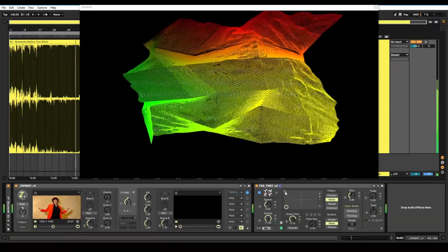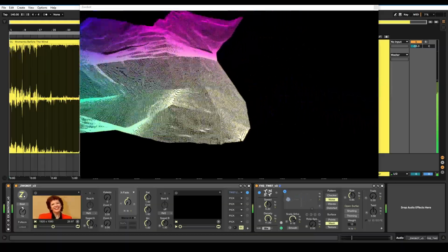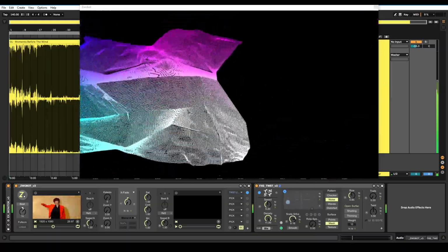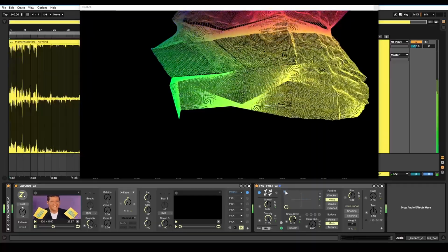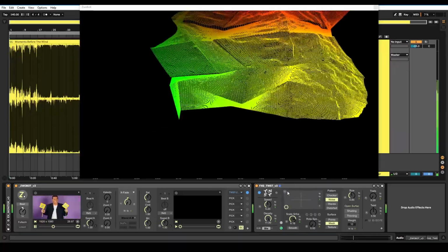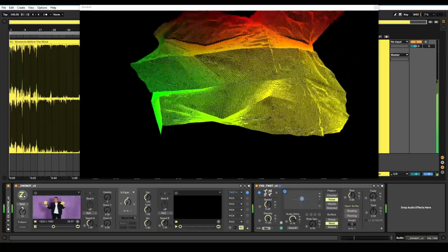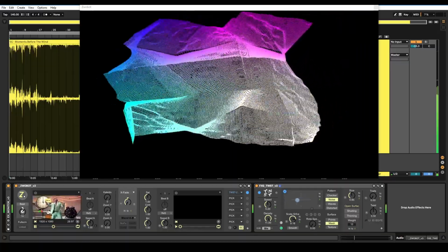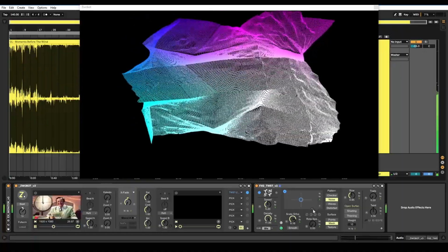If you click this plus button you get another grid, and this allows you to change the position of the shape. So you can change the position on this grid and then press the plus button again to go back and change the rotation on this grid. On the rotation one, the default is in the center, but it's quite difficult to manually get it exactly back there, so you can press this R button to reset it.